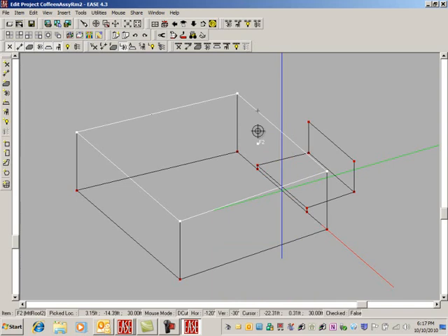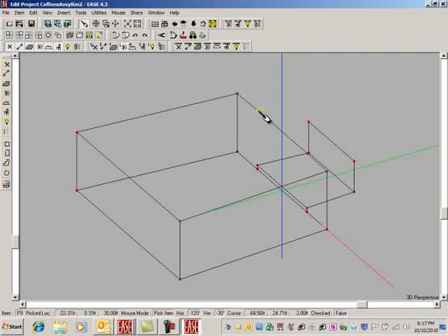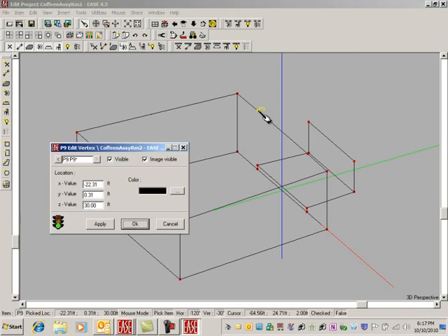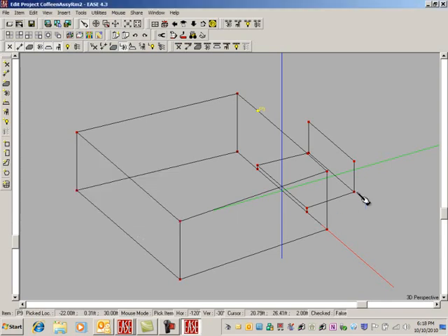So here I have my proscenium opening. And the ceiling begins at this point. Now there is then a surface right here, a face. Well, we could make that face here. Let's do that, F. And this is an inside face again, start anywhere. Here, to there, to there, to there. Create that face, yes. Chipboard, okay, done.